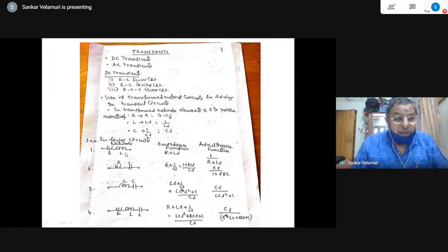So the transformed network elements in the circuit, not the branches meant as the cotree or spanning tree branches, the elements. Take the RL series circuit: R is changed to R, L gets transformed to Ls, so R plus Ls. The reciprocal of that is the admittance function.